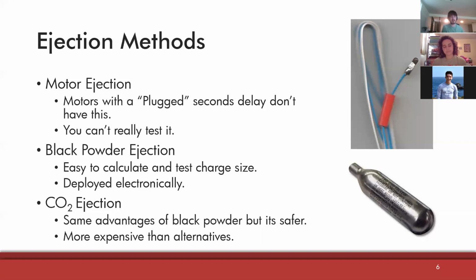It does work well as a redundant ejection mode though, so there's always the option to do that. It is important to note that if your rocket motor has an ejection delay of plugged, that means there's no ejection on it. I know that's something that has confused a lot of people.